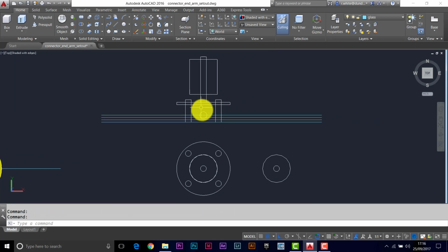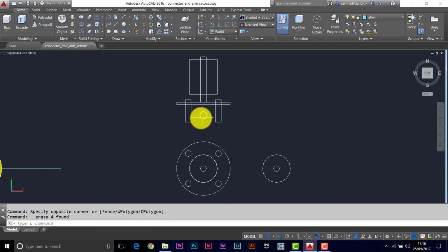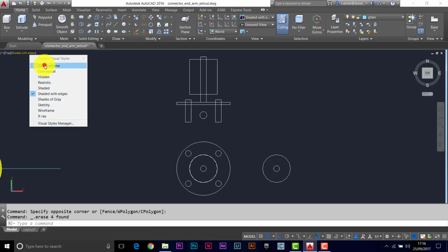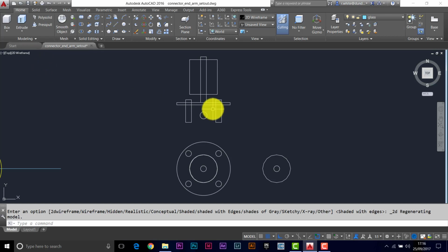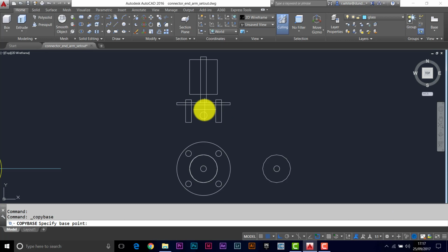Okay, so what I'm going to do is lift this off the deck and put it in position vertically above the plan of this object. I'll get rid of the glass, don't need to see that now, we know where the glass is. This is a setting out point, so I'm just using 2D wireframe until I get everything in place. Turn that into a block, so Shift Control C. It's asking me for a base point, so I'll use the center of that circle and then pick up the 2D work. I can leave that behind.